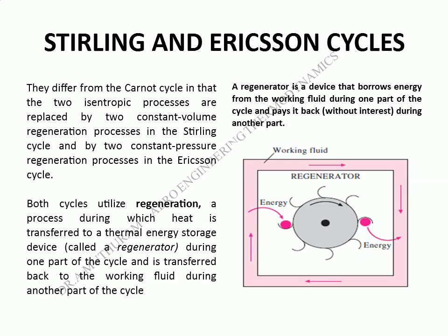Both cycles utilize regeneration, a process during which heat is transferred to a thermal energy storage device called a regenerator during one part of the cycle and is transferred back to the working fluid during another part of the cycle. The regenerator is a device that borrows energy from the working fluid during one part of the cycle and pays it back without interest during another part.